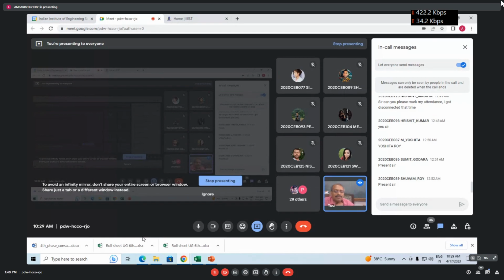So what is the friction part that is coming? Pi into 0.5 into 10 into 25 plus 10 into 40. So why is alpha 1? Alpha is 1 because the C value is less than 40. Up to 40, the alpha value is 1, and after that it gets reduced. The chart is given in IS 2911. Have you gone through it? Yes, sir, it is there in the chart. Intentionally, I have given values 30, 25 and 40 so that alpha will be 1.